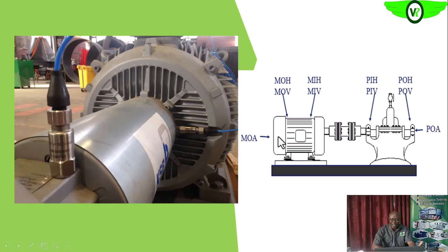So you see we have the non-drive end, which is the outboard end of the electric motor. Okay, so this is the inboard, which is this, where you have the coupling, and that is what we have here. So this is the inboard end of the motor. The other end of the motor, okay, at the back, is the outboard end of the motor. So we have the inboard for motor, we have the inboard for your pump, and the outboard for your pump.